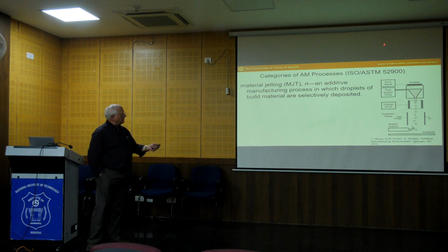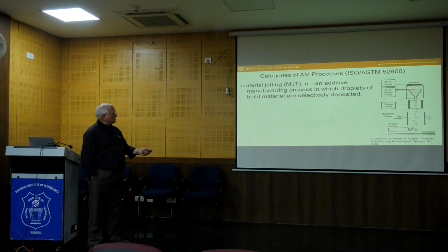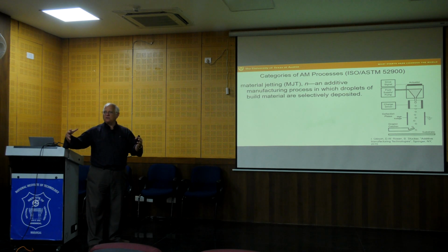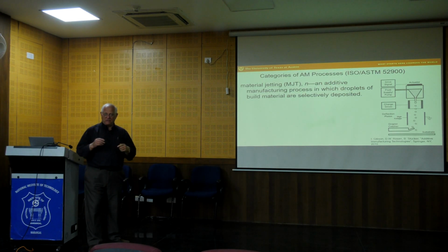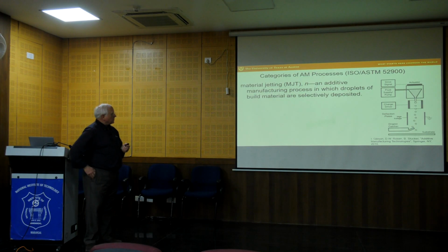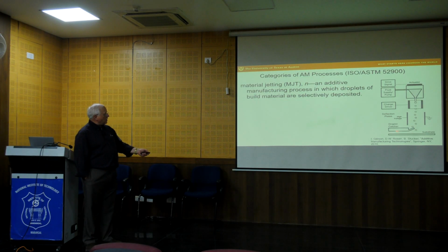And the distinction being that in this case, the unpolymerized material is up here. It goes through a nozzle which, with this charge driver, produces droplets. And then the droplets are squirted down to the substrate here to build the part. And it's this area down here that's completely bathed in ultraviolet light. So the droplet splats on the surface, and it's immediately polymerized by the UV light. And of course you see here this droplet catcher.